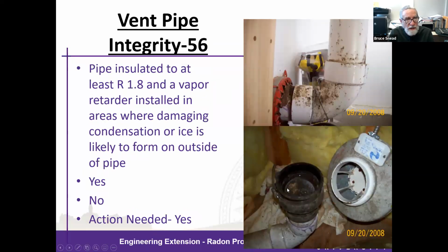Is the pipe insulated where necessary? If it runs through an attic, either in a hot climate or a cold climate, it may be necessary or appropriate to have insulation to prevent condensation either on the exterior or the interior. And that's a climate-driven issue. But you can see from these photographs that condensation and mold can occur on these radon piping systems because of the temperature of the air they're moving inside and the temperature and conditions of the space through which the pipe is configured.